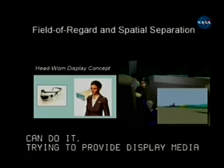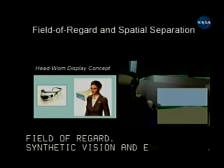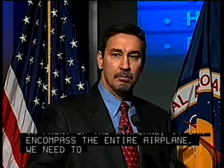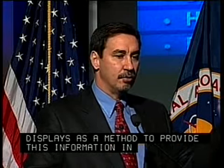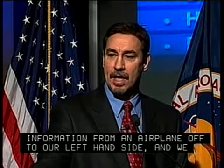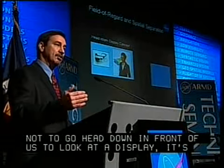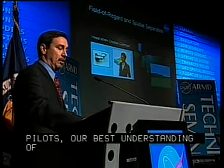Remember that synthetic vision and enhanced vision is not necessarily just focused in a small part of space in front of the airplane. It actually can encompass the entire airplane. So we need to provide a way, and we use these head-worn displays, for instance, as a method to provide this information in a spatial location. In other words, if there's information from an airplane off to our left-hand side, and we want to most intuitively understand who's giving us that information, it's not to go head down in front of us and look at a display, it's to actually put the information over to the left-hand side. That way the pilots best understand the information as well as its impact or potential impact it may have on our flight.